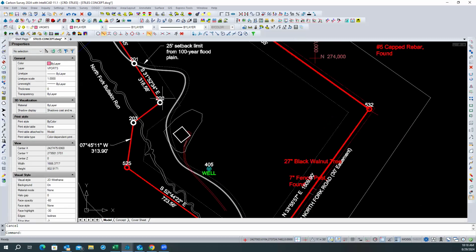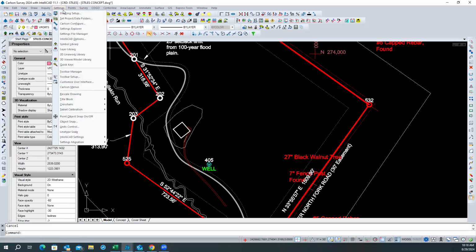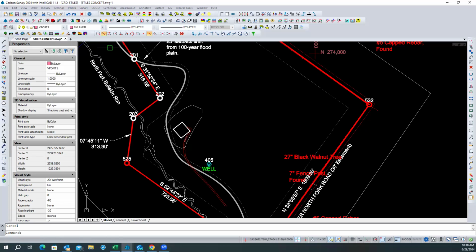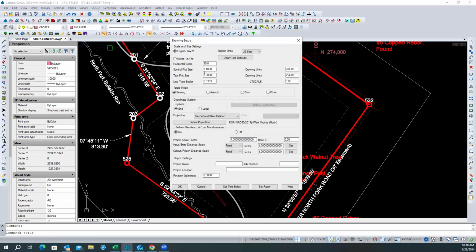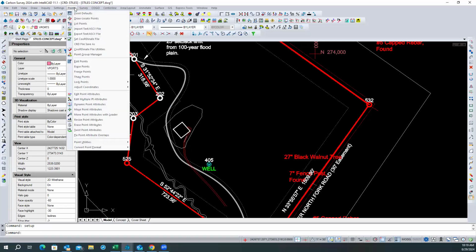It looks like these were done maybe with that not on because that text label is way too large to be at this scale. But if you do, and you're using annotative, all of those labels, everything just resizes itself to be the size of this right here, the symbol and the text at this scale. And it will automatically follow if you're using annotative when you do that.